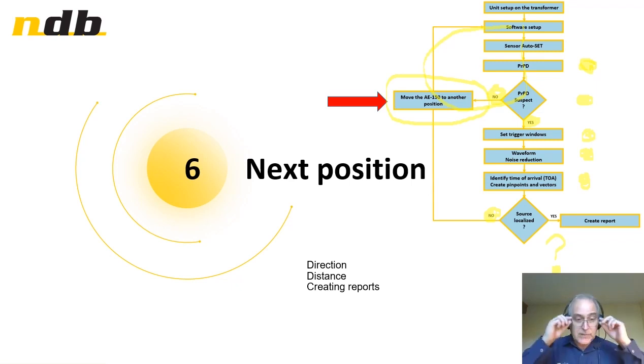But something to remember, if there's nothing, it doesn't mean that the transformer does not have PDs inside. It means that today, at the inspection time, nothing was suspicious. It doesn't mean that tonight or this weekend, when the activity will be different, let's say the load will be less, the voltage will be higher, the humidity will get in, we may get PDs at this time. But right now, at inspection time, I am looking at nothing.